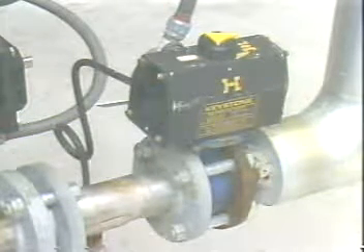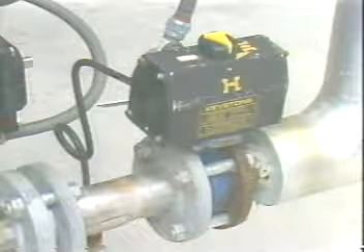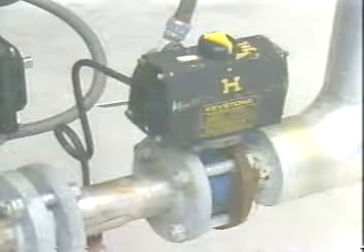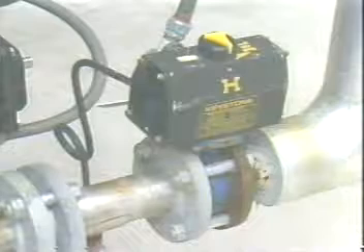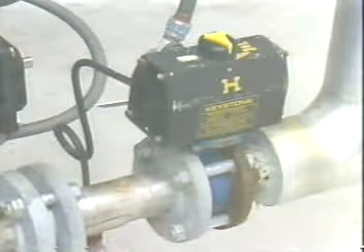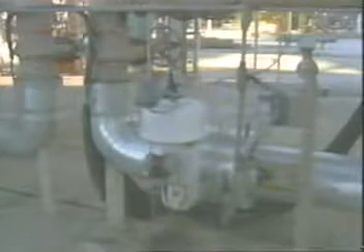This is the case when the control action is taken to prevent an undesirable event from occurring. An example might be one in which a flow path is opened in order to relieve high pressure. So you can see different control applications require different control valve designs. Similarly, different control valve designs may require different types of actuators and positioners.